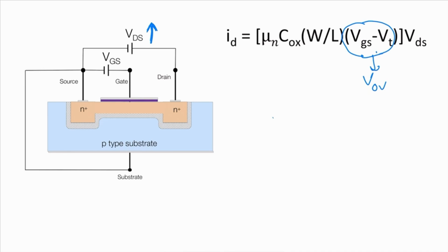First, just think about it like this. Suppose there is no VDS. If there is no VDS, then what is the gate to drain voltage? VGD is equal to VG minus VD, or we can write VGS minus VDS. Why? As VS will cancel, then VG minus VD. When I didn't connect any voltage source on the drain terminal, that means VDS is equal to 0.